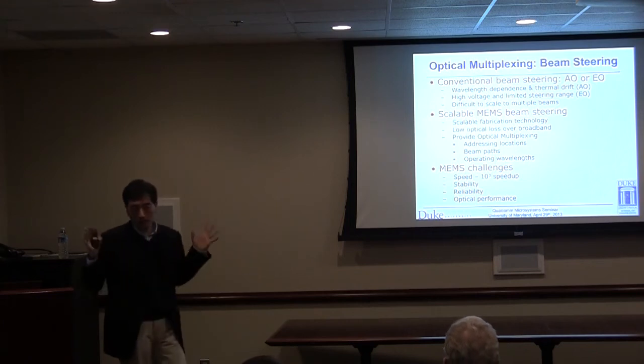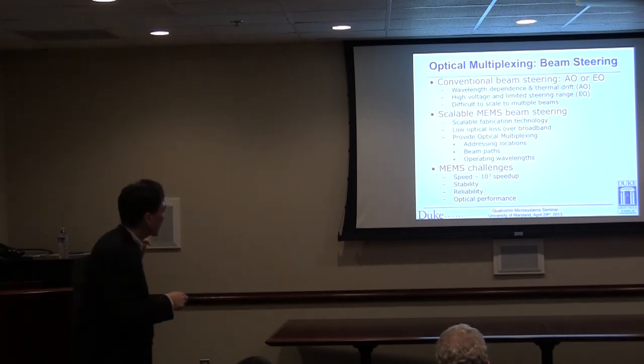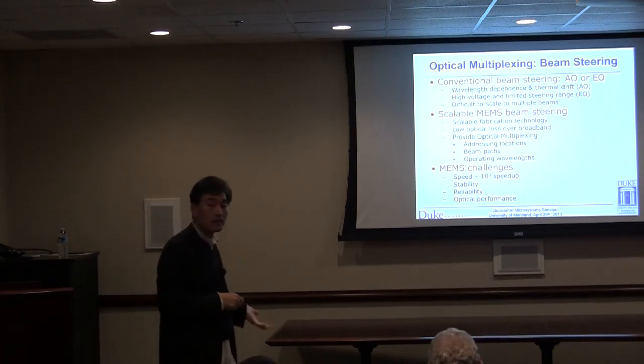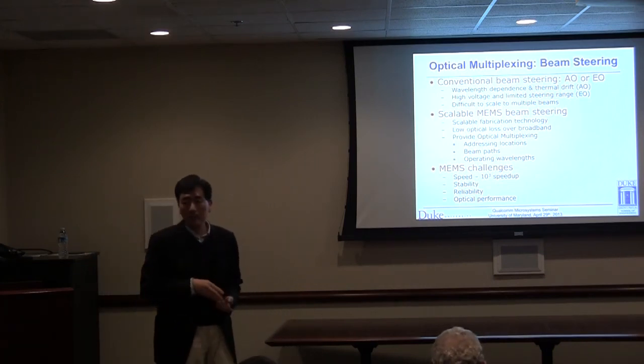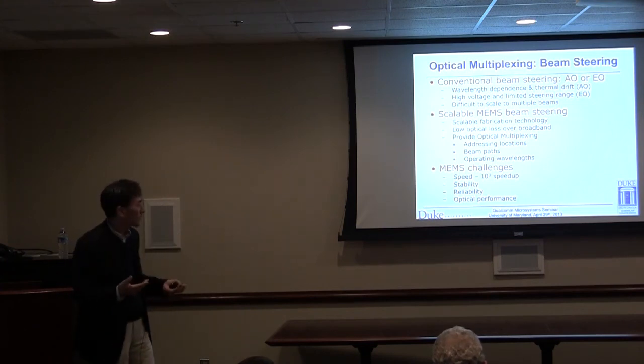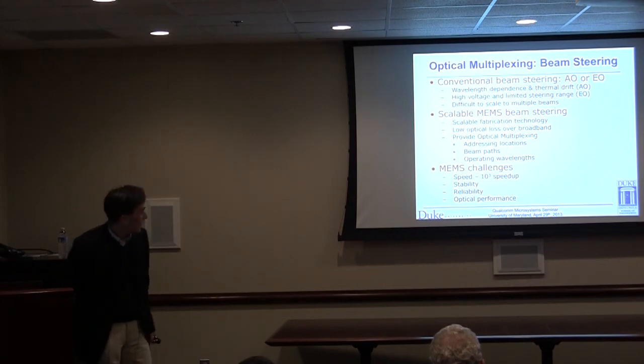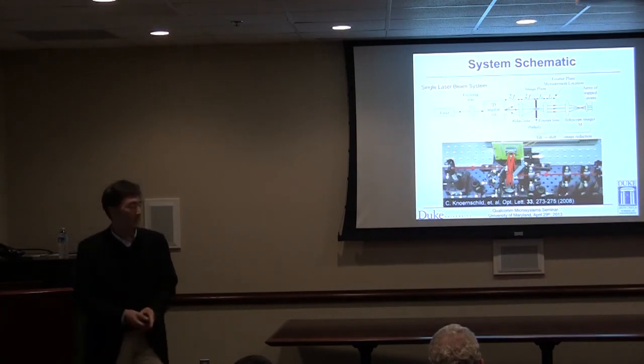These optical switches I showed you, based on tilting mirrors, take milliseconds to tilt. But for atomic physics, we really want them to tilt on a microsecond time scale. So we had to make these mirrors move 1,000 times faster, and mechanically, things moving at roughly megahertz is really not very easy to do. But nevertheless, we can optimize the system to do that.